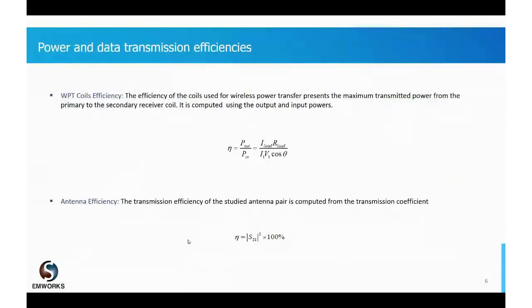The key parameters that we're looking for, number one, is how efficient our coils are in power transfer. The more efficient, the less power required, and the safer the whole system is going to be. You don't want to have so much power in the presence of biological tissues. So there are two efficiencies. One is how efficiently we're powering the implant, essentially the power that's injected in the exciting coil versus the power that's received, and we'll show you how to simulate this.